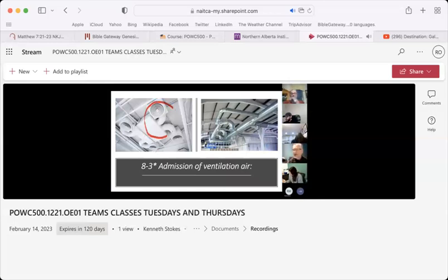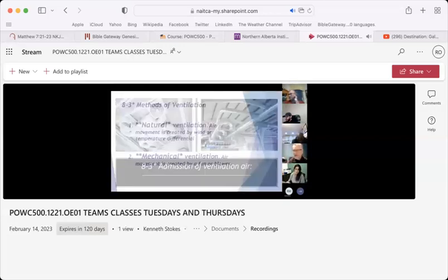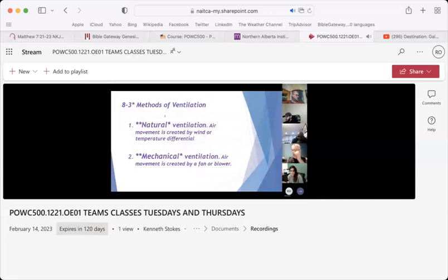So you're going to see a lot of equipment that looks pretty strange and wonderful and does all kinds of strange things. As the video pointed out, there's some various ways to introduce the air. Remember, we have 2 main methods of ventilation: the natural type, air movement created by wind or temperature differential only, no fans, or mechanical. And mostly we will look at mechanical.